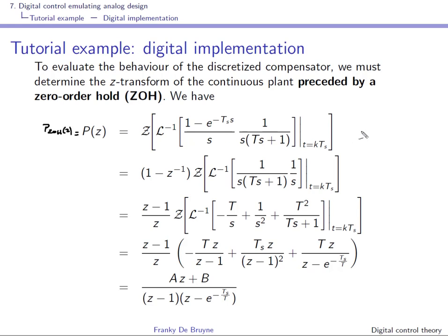and we had seen that you can obtain it as follows. So here you have the original continuous time system. This is how you take into account the zero order hold, right? And we had seen that you could rewrite this differently, and you could also obtain it by considering that this zero order hold equivalent is exactly also the step invariant equivalent description of this process, right?